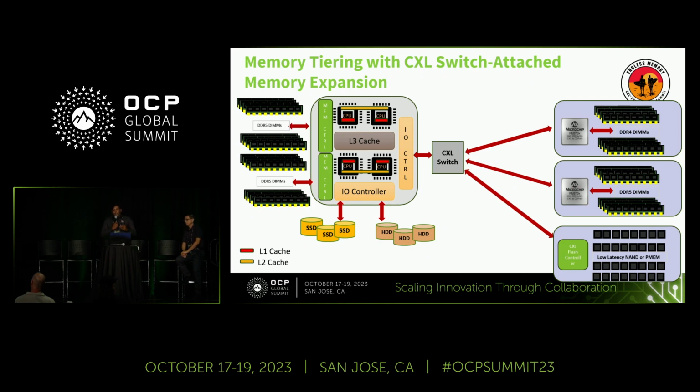So along with these system architectures, what CXL enables us to do is also provide a unified interface irrespective of what memory is behind the controller. One of the challenges with, for example, NVDIMM is enabling the support for it in the ecosystem. What CXL does is it gives a unified interface for the ecosystem vendors to integrate in their development flows. And behind the CXL controller, you can have DDR4 DIMMs, DDR5 DIMMs, or even flash, for example, the Optane replacement.